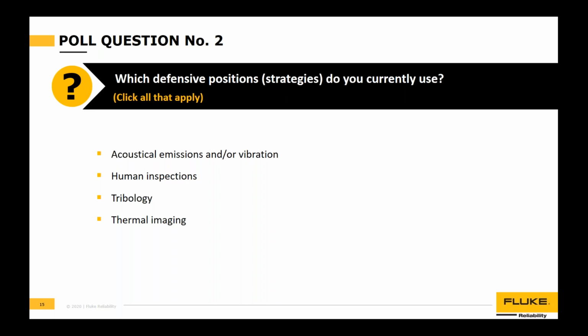One of the biggest failures I've ever experienced was on a giant hydraulic press, and this thing had 4 cylinders that were about 20 feet long and about 4 foot diameter. Some big boys. And each one of those to rebuild was about $70,000. So we were actually able to detect the seal failures using the tribology before we actually could see it or even hear it with acoustical.